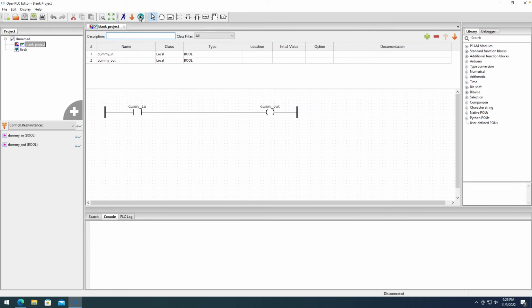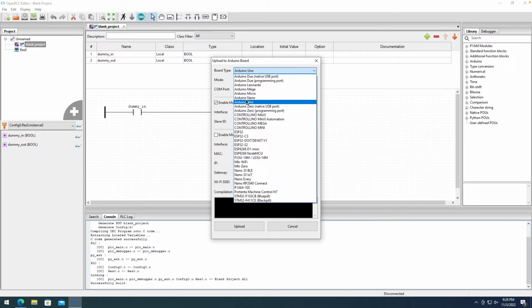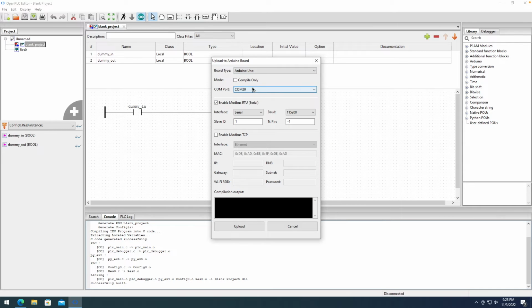All I have to do is compile this project for the Arduino board. Now I go ahead and make sure that I have the right board selected. It's Arduino Uno on COM29. But here's the important step, right? You see here that there are two versions of Modbus. On the Arduino Uno, I'm using the Modbus serial version because it has no Ethernet or Wi-Fi connectivity. But I need to set this up exactly as the template is configured.